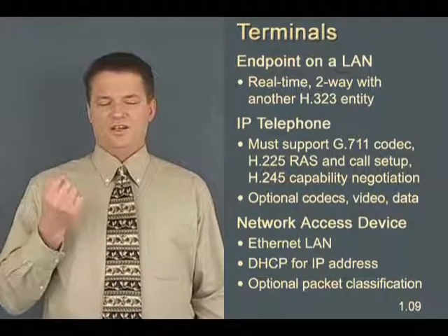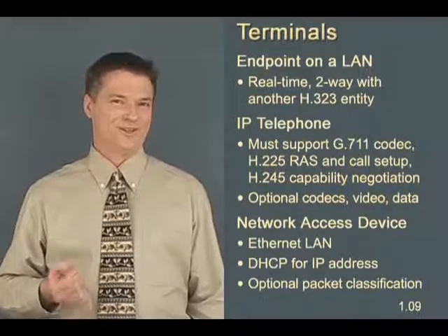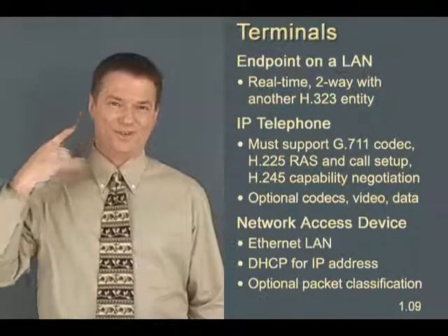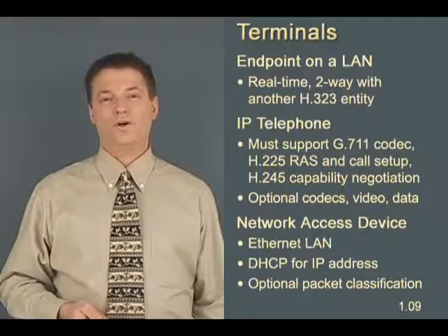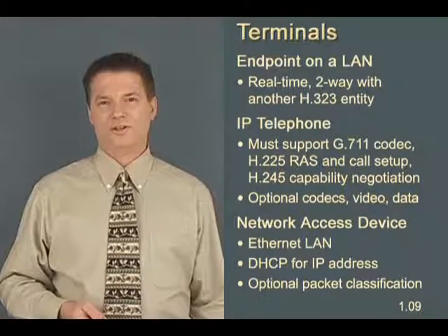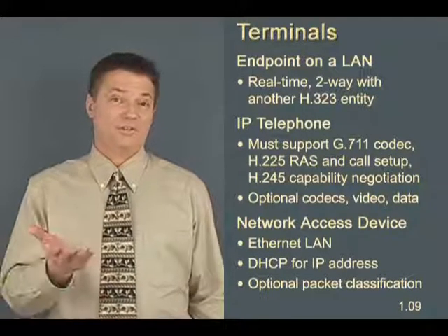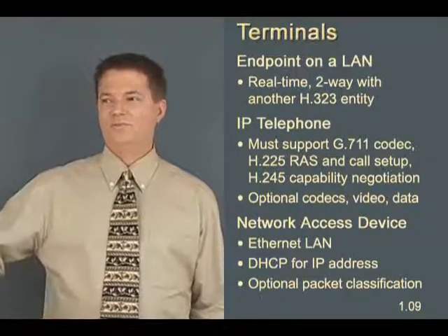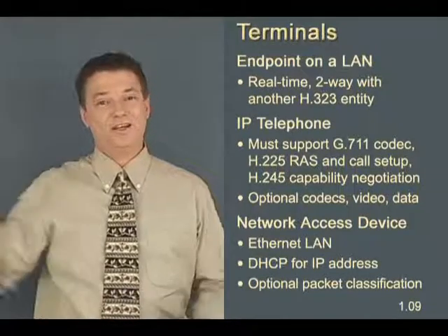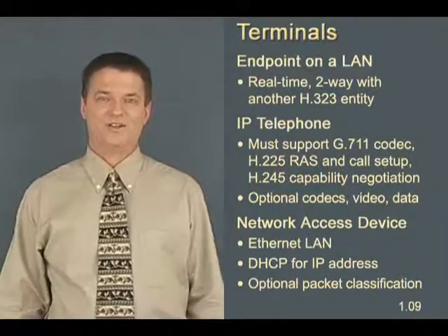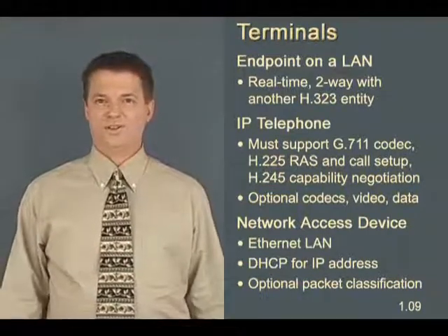Now, in addition, when we start talking about quality of service, and what we're really talking about there is figuring out how to get quality of reconstructed speech at the far end, what we're going to see is that some of the techniques required for doing quality of service require the terminal to tag the packets that are coming out of it as being voice packets. So that would be an optional function on a terminal if we're going to end up using some sort of network quality of service technique that ends up examining the tags on the packets. It's the terminal that has to put those tags on to start with. The terminal is a thing that spits out IP packets with coded digitized speech in them.